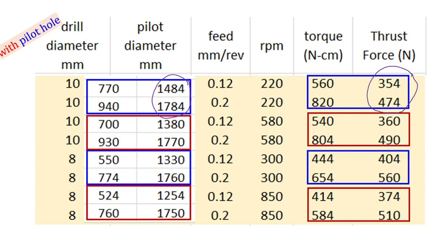That means that small chisel edge is primarily generating so much of thrust force in drilling. So if you do not allow the chisel edge to participate in the cutting process by putting a pre-existing hole, your thrust force on the cutting tool goes down tremendously. It is almost around 1500 and here it is around 300. So it is very less.